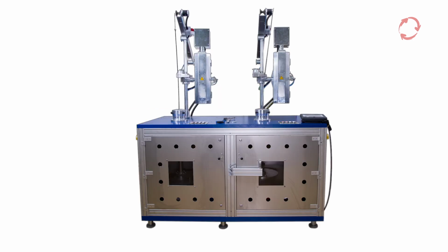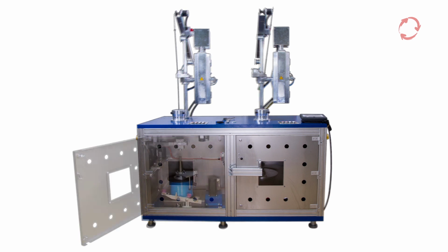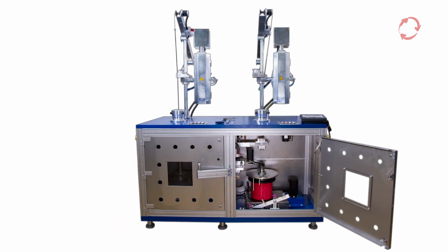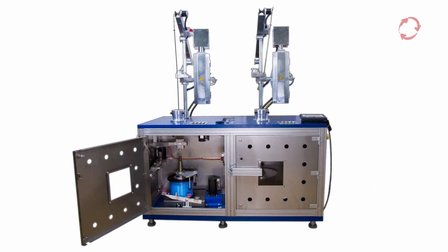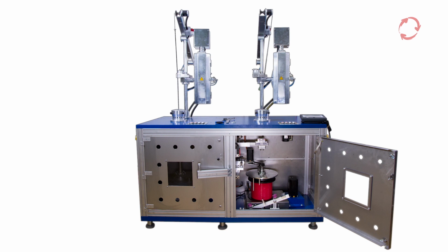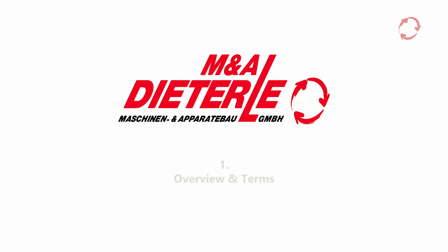The spiral machine essentially consists of two spindles that function independently of one another. Monofilament spirals with round and rectangular cross-sections can thus be manufactured, spirals wound simultaneously to the left and to the right. When using round monofilament, right and left-hand spirals can be produced on each spindle. For technical reasons, when using monofilament with a rectangular cross-section, only right-hand spirals can be produced on the right side, and left-hand spirals on the left side.